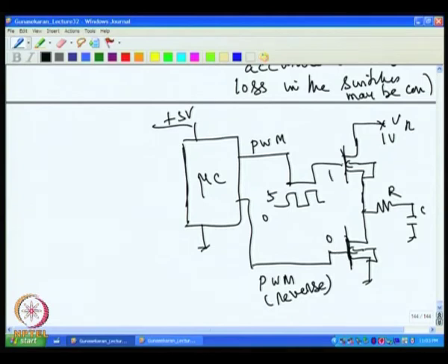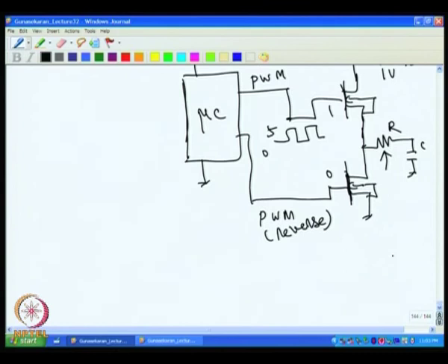This kind of switch arrangement will eliminate the problem due to the power supply drift and the on resistance. These switches can be very low on resistance switches, so that there is no error due to the switch, and the resistance R can be selected much larger than the on resistance of the switch.